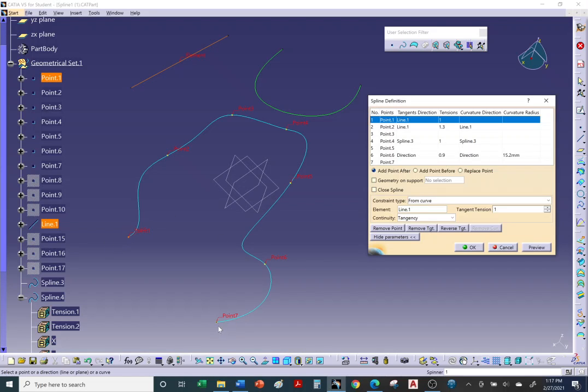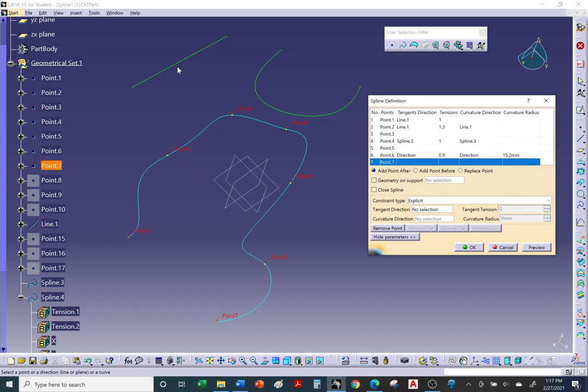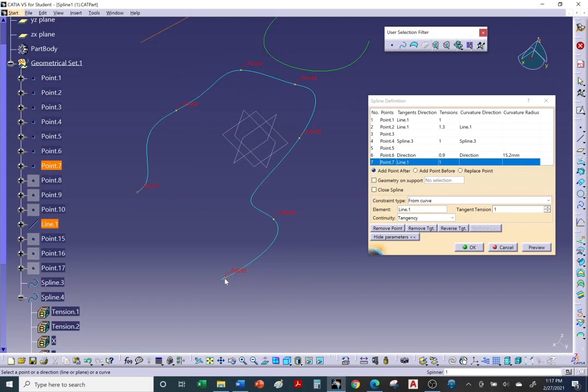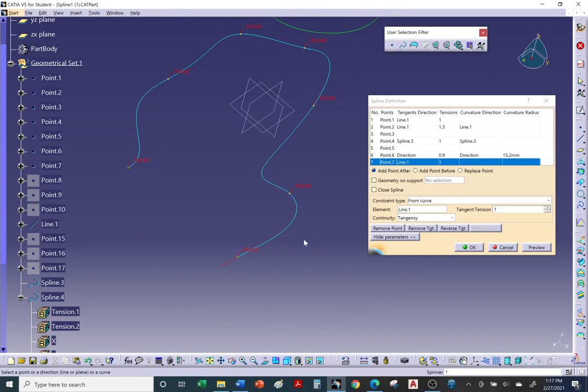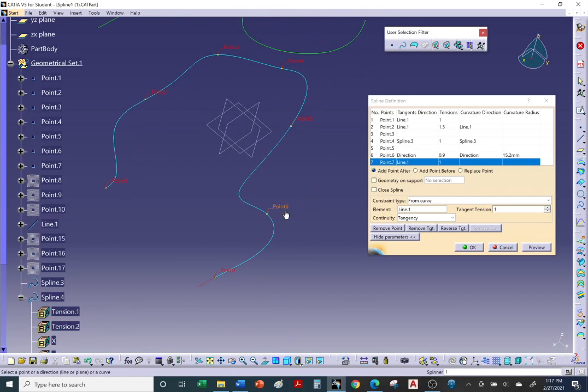All right. Could do the same with the other point, point number 7. Okay, let's go in the X direction. Now it's hard to see, but it's actually flipping, it's going in the wrong direction. If we zoom in, be aware of this. If I zoom in, see how it's not going in the right direction? It's twisting and turning. I'm like, nah, let's flip it. There it is. There's the red arrow if you want to flip it again. Okay, so it looks a lot better. Maybe this turn is a little too much, but you do encounter situations like this when you're installing cables, wire harness.